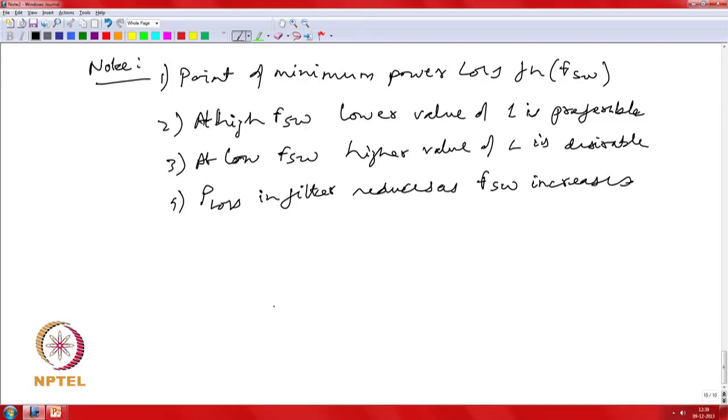In many designs you often ask what is your switching frequency, and you might say 10 kilohertz or 20 kilohertz or some number. So later on you can actually justify why you selected a particular switching frequency through such a loss calculation, which leads to what is the best switching frequency that the power converter can operate.